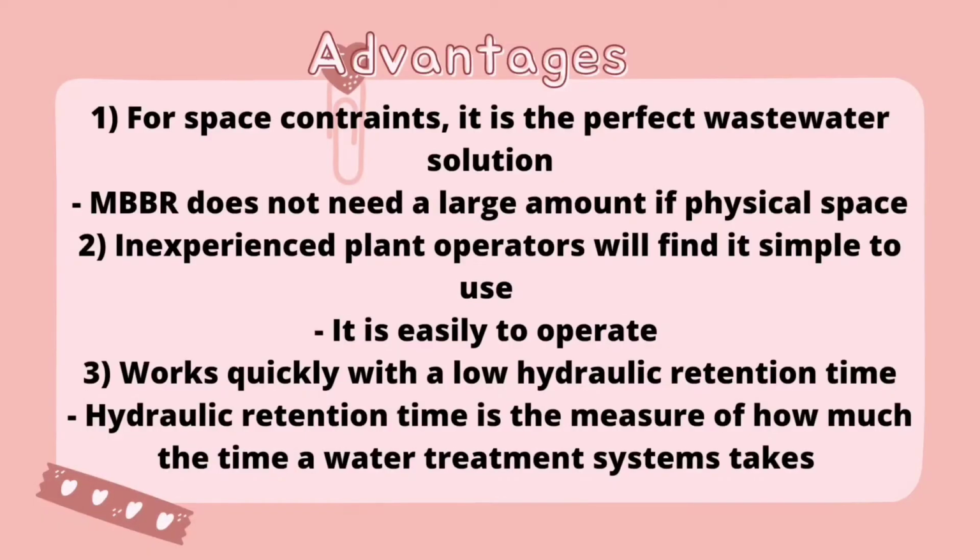For my part, I will explain about the advantages and disadvantages of moving bed biofilm reactor. The first advantage is for space constraints, the perfect wastewater solution. One of the most significant advantages of MBBR is that it does not need a large amount of physical space. In fact, when compared to other biological wastewater treatment systems, MBBR is known for its minimal footprint. An MBBR tank can treat the same amount of wastewater as a trickling filter or activated sludge tank while being a quarter of the size.